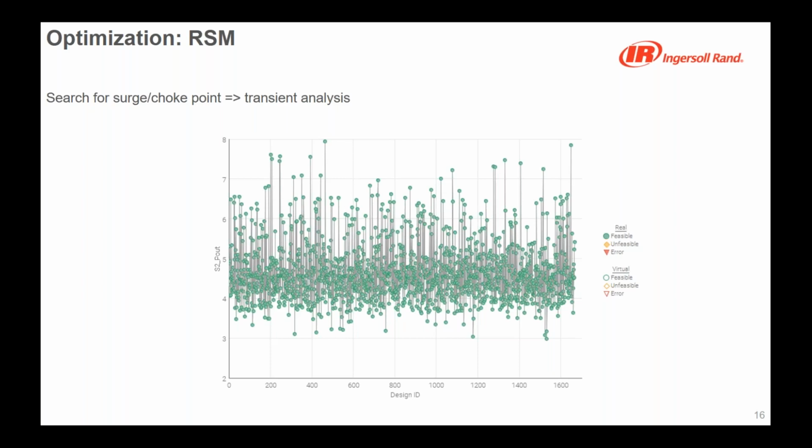condition. So what this graph told us was that there may be some cases that are wrong in terms of RSM analysis, so you do not necessarily believe too much, but it also gives you an indication on which area you can more likely get a surge in extreme condition. You have to think that among the parameters that we use to run this RSM, there are also pressure and temperature on top of IGV angle variation.